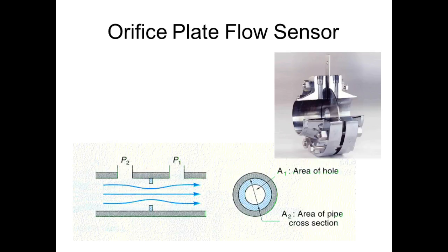I could bring one pressure on one side. I could put the low pressure on the cavity, high pressure coming in, and then the output of that sensor would be what? It would be proportional to flow rate. You understand what I'm saying? Yeah. Pretty neat. This guy creates a pretty good deal of opposition though.